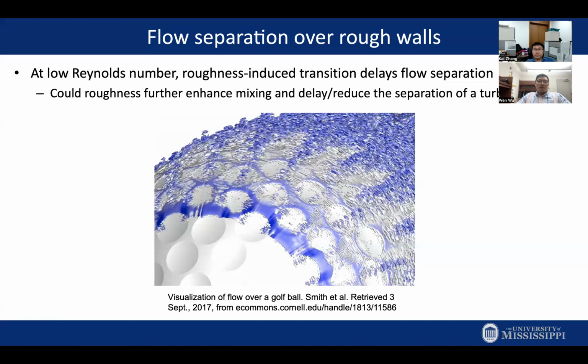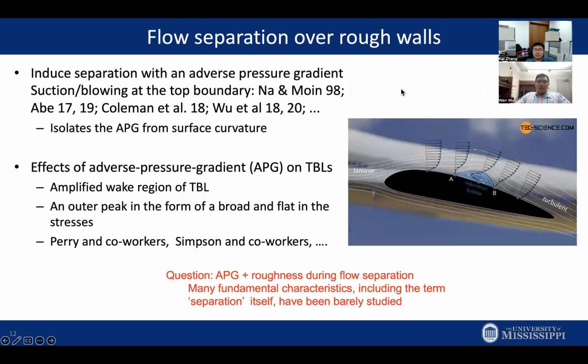We all think roughness can further enhance mixing. So does this additional mixing delay or reduce separation? If it's enhancing mixing, you can bring more high momentum to the wall, and hopefully it can reduce separation. That's the question that we're trying to ask.